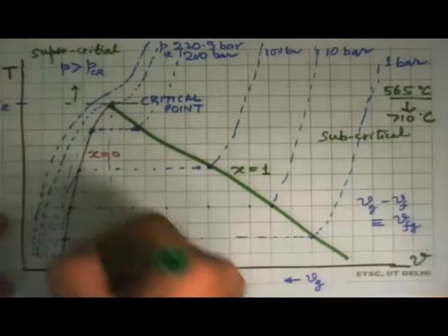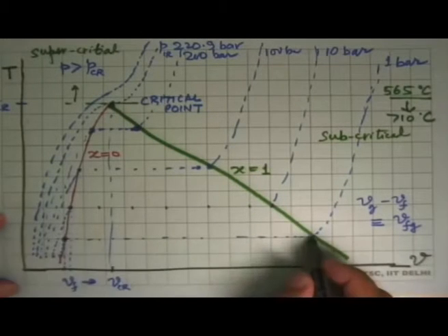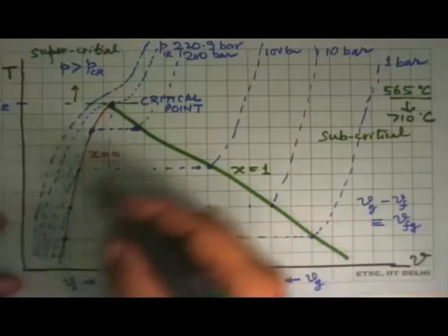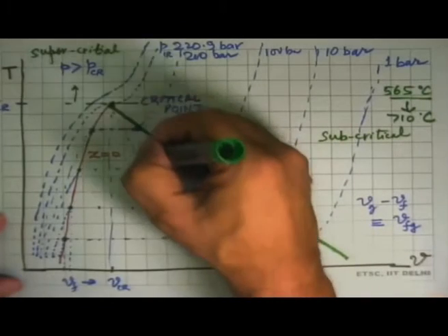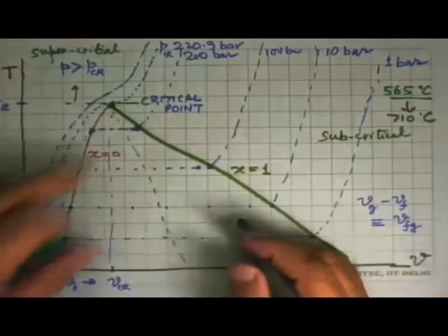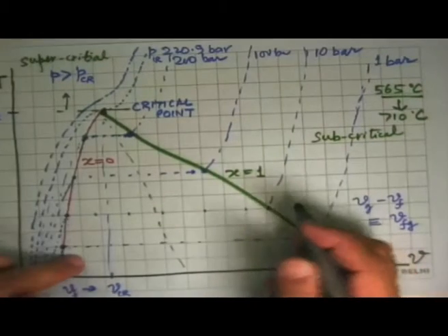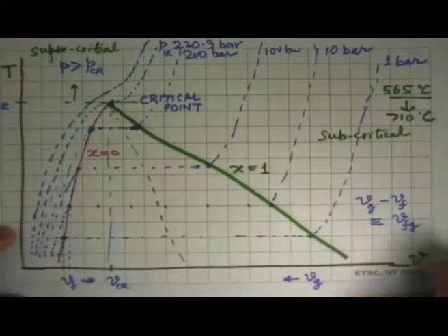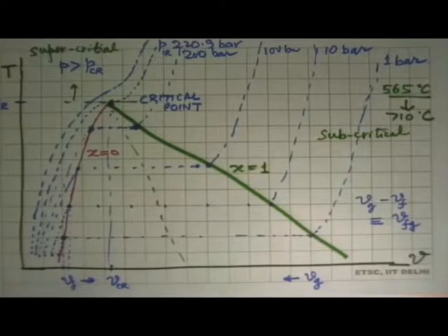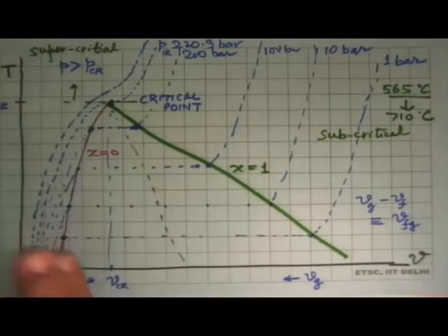Okay, so what it tells you is that as you go from left to right, x goes from 0 to 1. So in this, one can draw lines which are somewhat like this, and say, well, these are constant dryness fraction lines. X is equal to 0.6 is this much, x is equal to 0.7, x is equal to 0.3, they are like that. Okay, all the definitions that we had are valid for all this discussion.